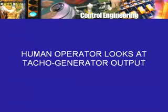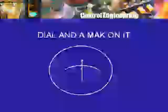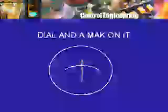Now we can bring in the human operator. The human operator can monitor the drive by looking at the tacho generator voltage. There can be a dial on which one does not have to write any numbers, but one can put a red mark or black mark or whatever. If the motor speed is 1500 rpm, the tacho generator voltage will be such that this meter pointer will be at that mark. And now the operator has to keep on looking at this instrument dial. Of course, he has to be given some means of making adjustments so that the pointer remains against that mark all the time. And the only adjustment that we can think of, given our situation, applied voltage is not going to be changed.